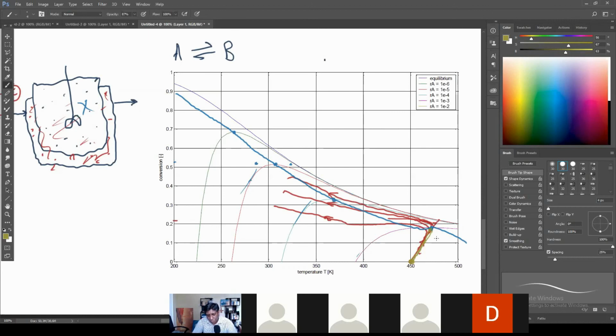And so we could do a small integration here. We could say, okay, we'll let this be adiabatic, and we can see here the conversion at that point, maybe it's 0.18. So we can solve our material and energy balances until we get X equals 0.18. And then we say, well, now switch on cooling. So let's start cooling the system down now. And now we know what temperature we want to apply next. So we can say, okay, we reached there. Now to get to the next point, let's say that's there, we need to get to this temperature. So that defines how much cooling you must do.